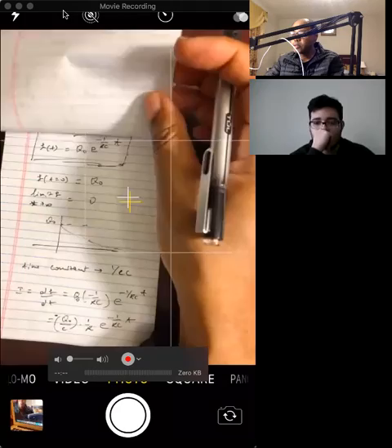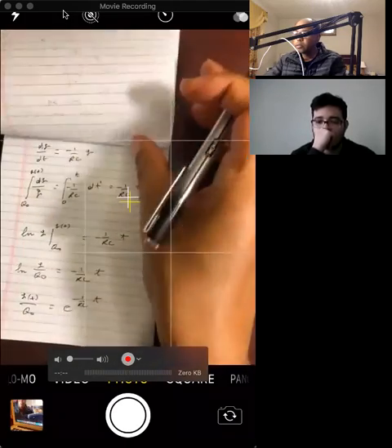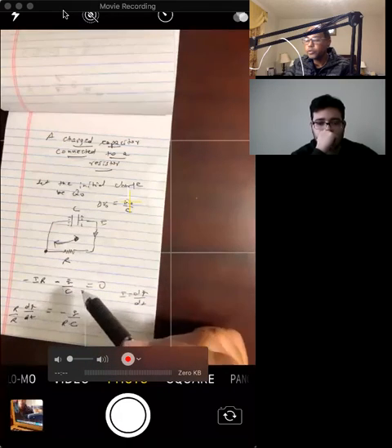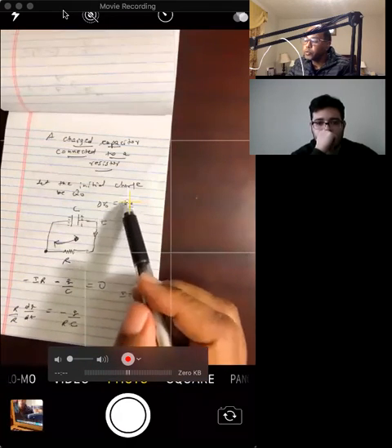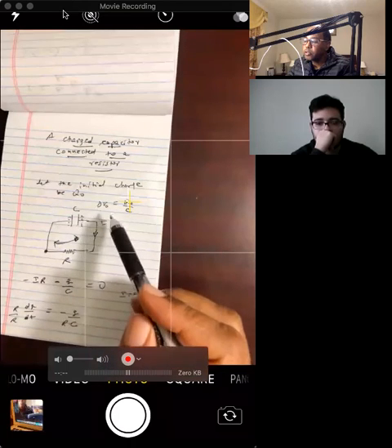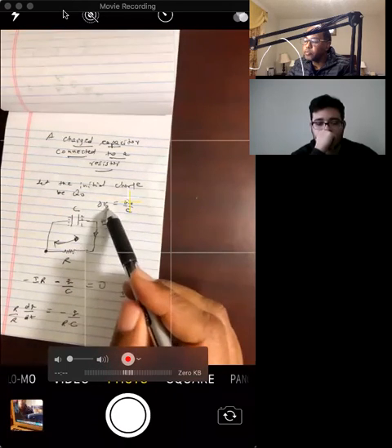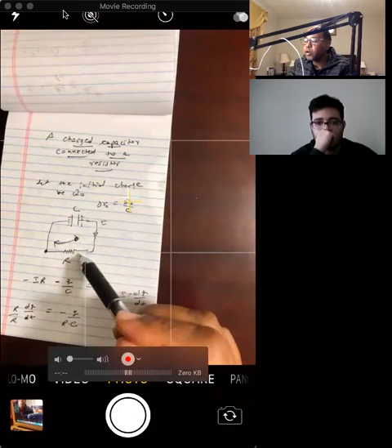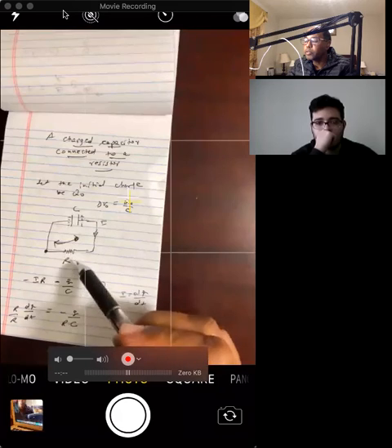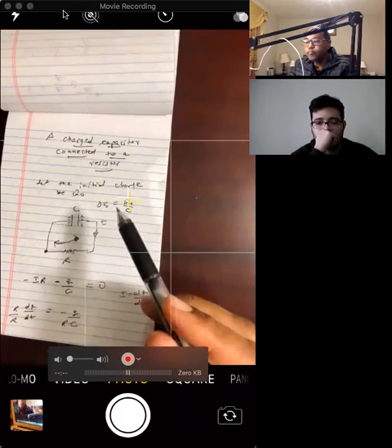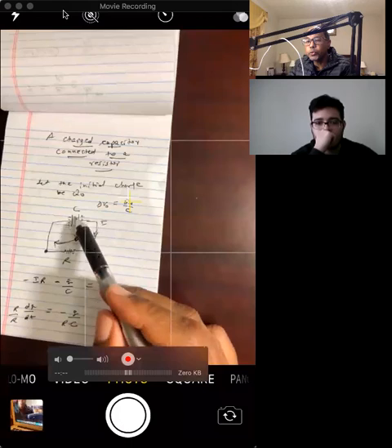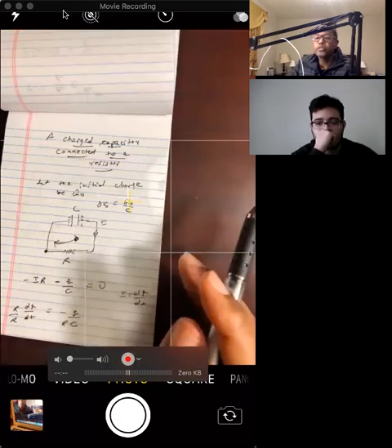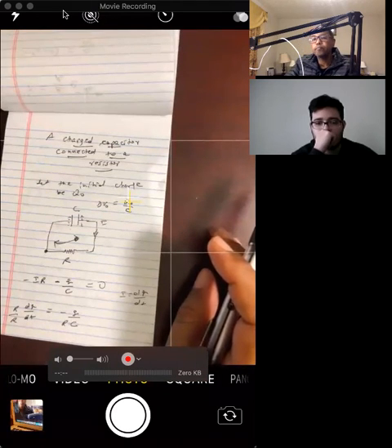So these are the properties of this kind of circuit. Let's summarize. You've got a charged capacitor connected to a resistor. What happens? You start with this potential difference, so the initial current is this potential difference divided by the resistor. So we've got a maximum current of delta V over R. As the charge decreases, the current keeps decreasing. Eventually, there's nothing going on. This becomes zero potential difference eventually. That is, the capacitor is discharged fully eventually.